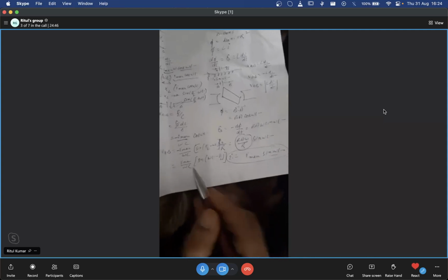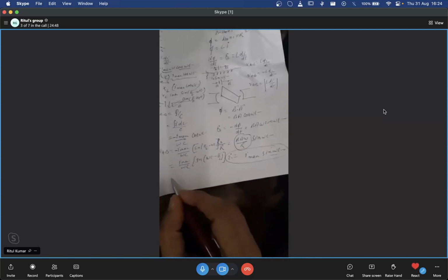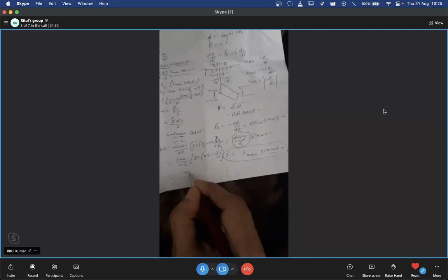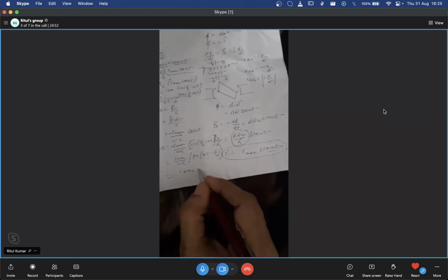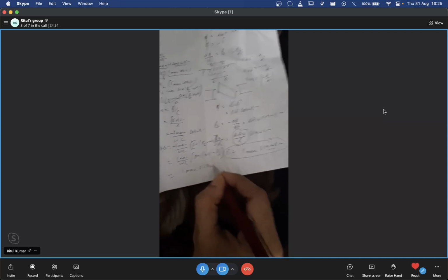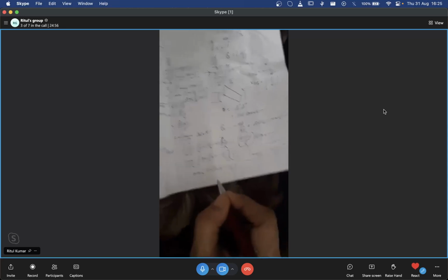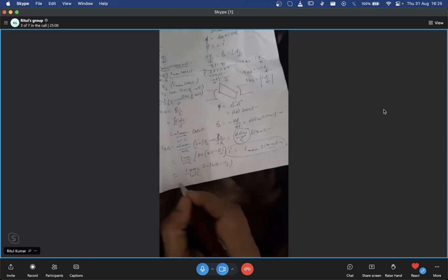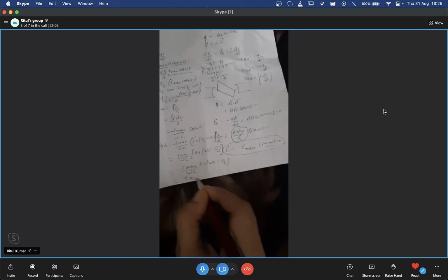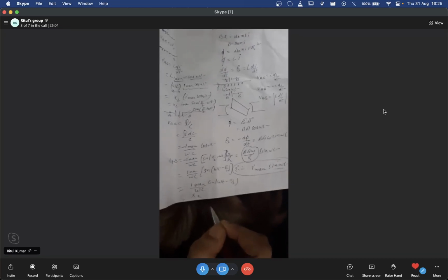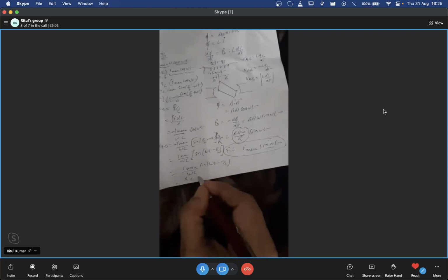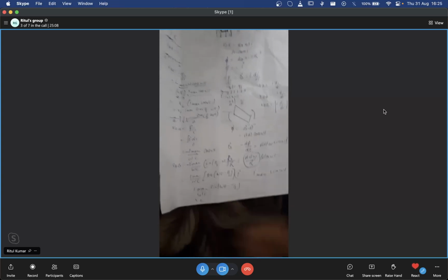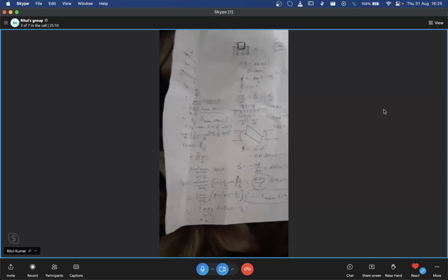Coming back to what in this case will be XC, we want to write again. Sine term taken, sine of the angle omega t minus pi by 2 taken, everything done. What term we are left with is omega C. So what can we write? XC is equal to 1 by omega C. What was XL? XL is omega L. Please write these down.